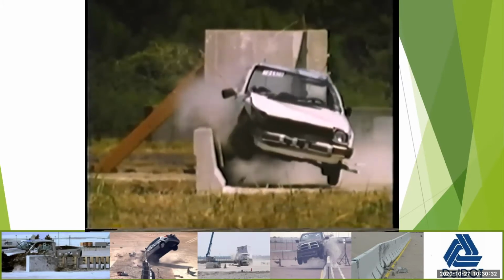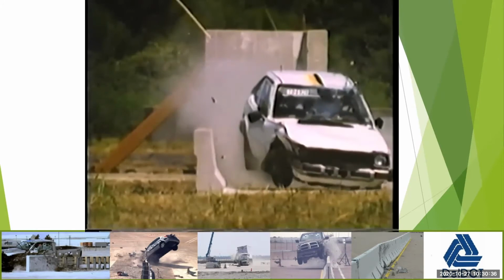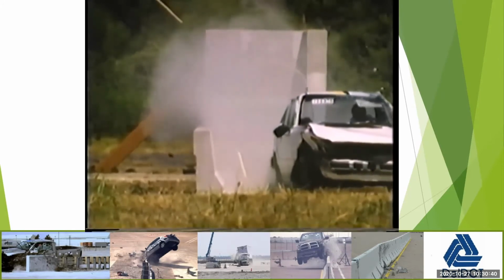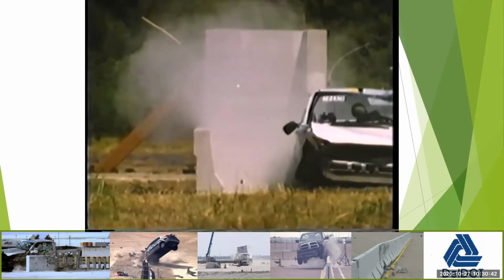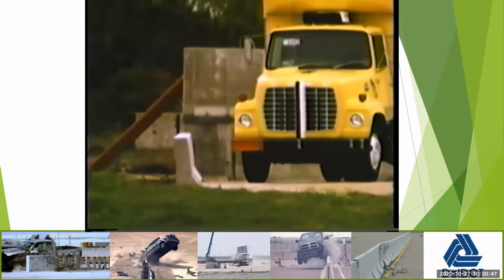F-shaped barrier dissipates energy by lifting the vehicle. The occupant responses in this small car test were somewhat larger than in the tests of the New Jersey shape, although they were still below allowable limits. The vehicle trajectory, however, was much better, minimizing the possibility of a second collision or a rollover.